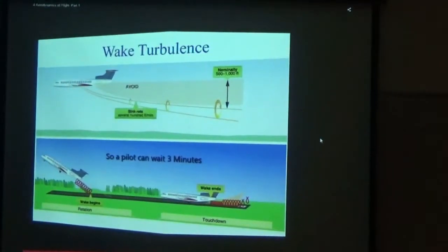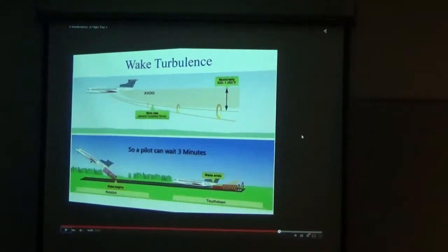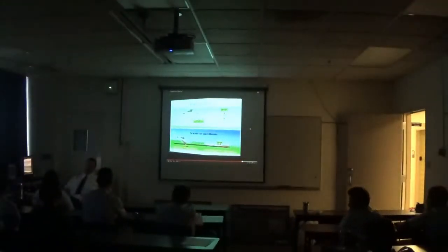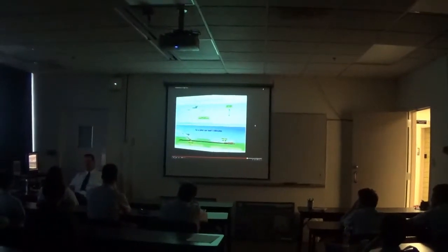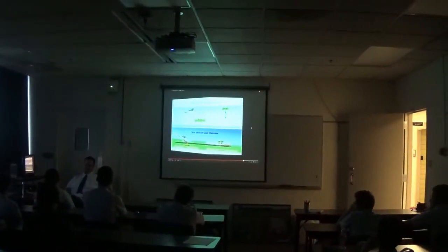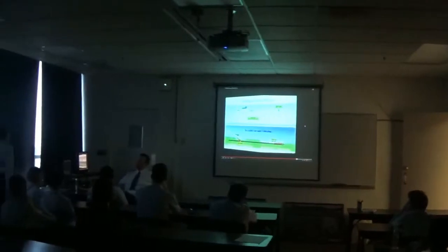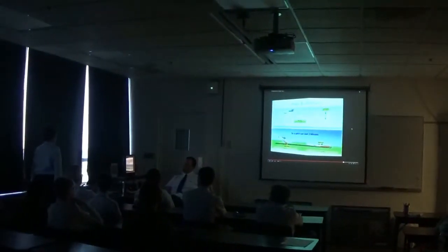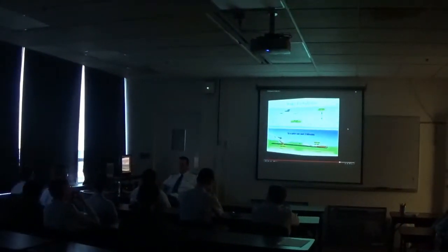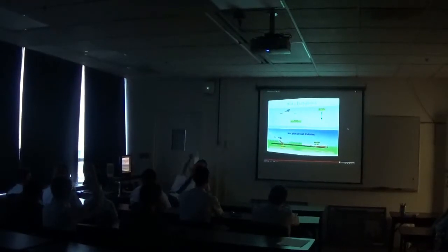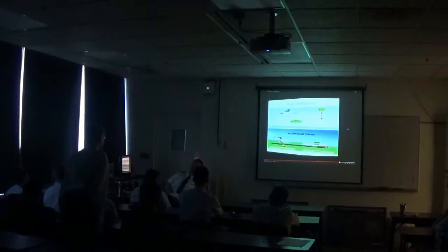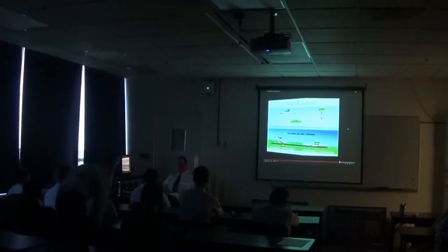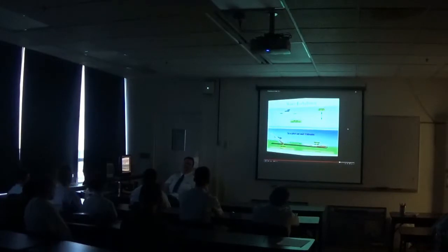Now, a bit more on the wake turbulence itself. It said the biggest wake turbulence created is when the aircraft is slow and heavy. Now, when is the aircraft at its slowest and heaviest? Cadet Master Sergeant Schreiner, when it's landing, sir? Incorrect. Yes? Sir, an aircraft is traveling slowest and heaviest on takeoff? Correct. That's when it's at its slowest and heaviest and therefore the most dangerous.